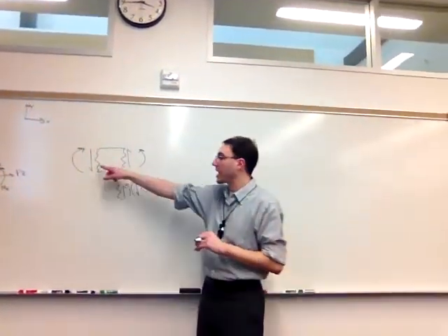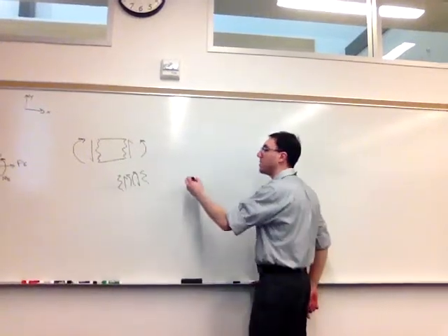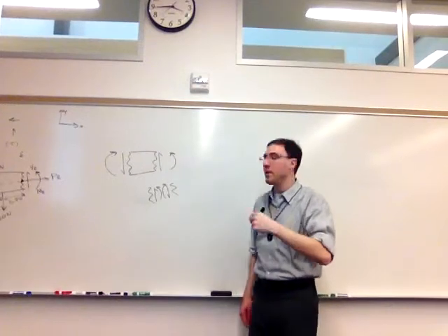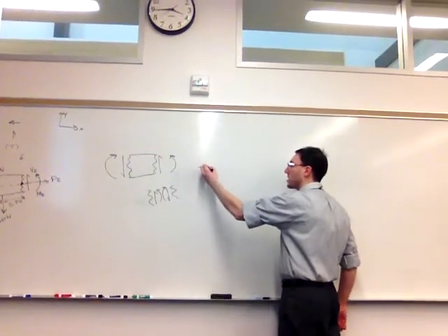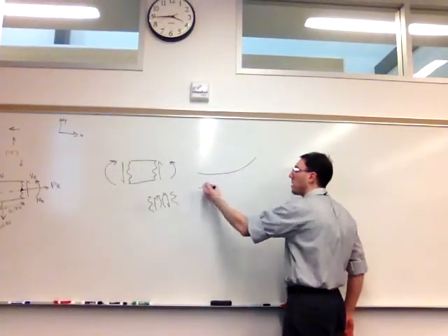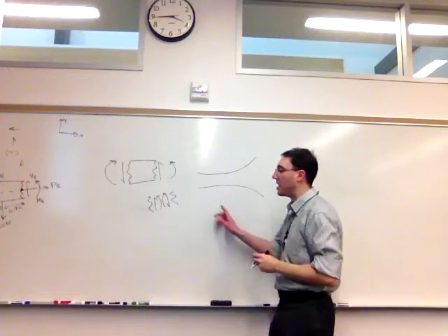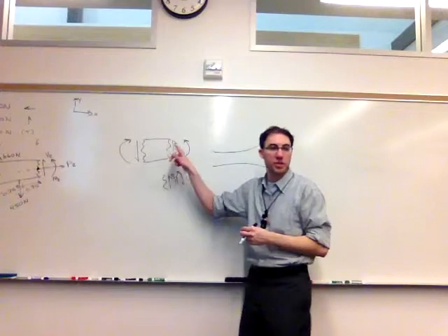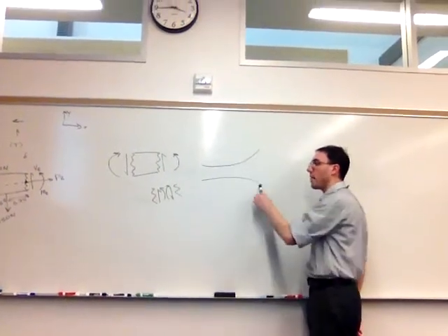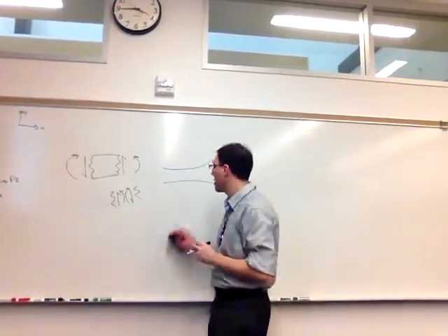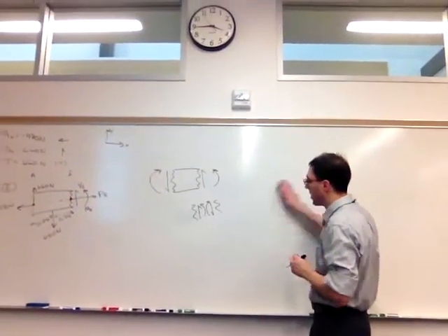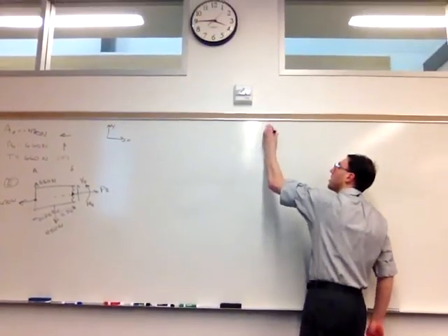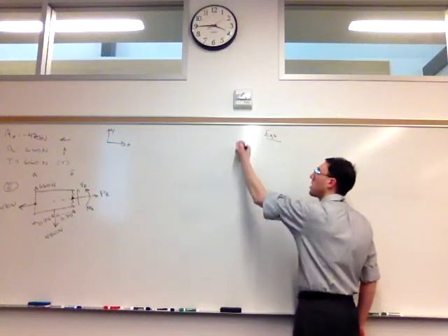But this particular convention is important once we get to beam bending, because if we have positive values for the moment and positive values for the shear, those will influence, is our beam bending upward or is the beam bending downward? And that's where the equations we're going to use depend on this sign convention so that we can interpret, is our deflection up or is our deflection down? So for this class, it's not as important. We'll enforce it in 213. Introduce three unknowns that we'll be able to solve for.